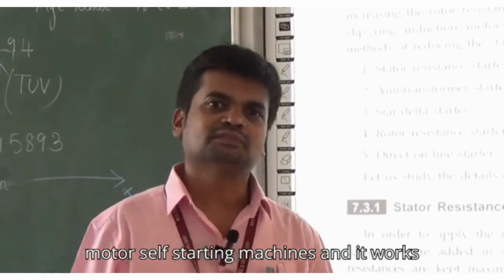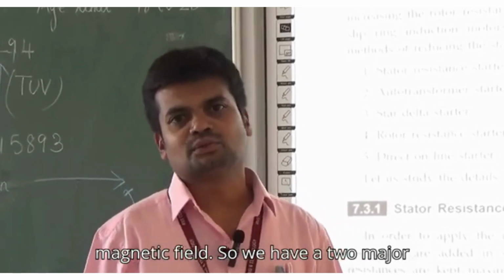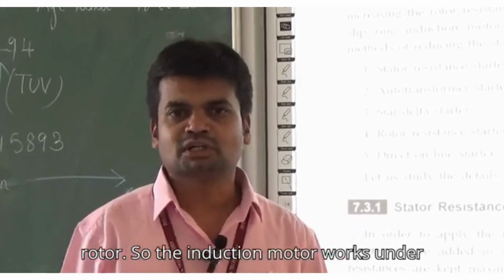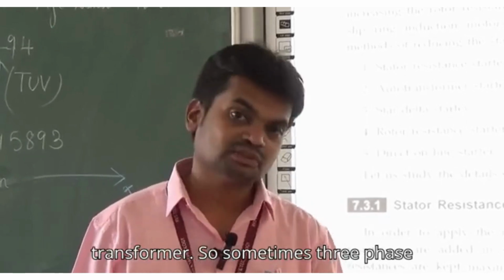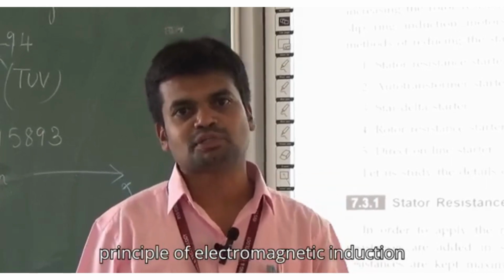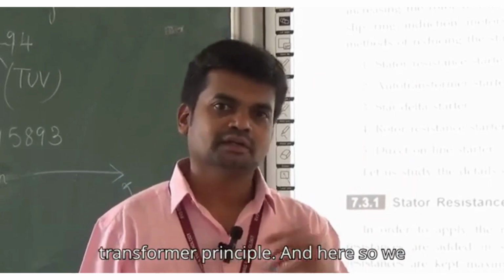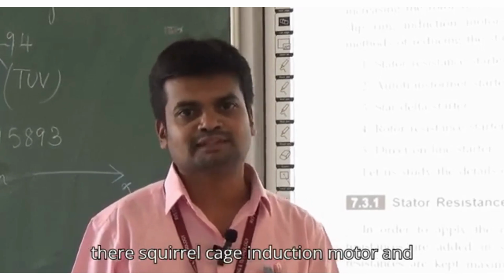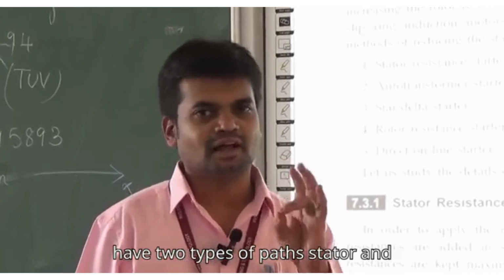the three-phase induction motor is a self-starting machine, and it works under the principle of electromagnetic induction with the RMF, rotating magnetic field. We have two major parts in the induction motor, stator and rotor. It's like a transformer, so sometimes the three-phase induction motor is also called a rotating transformer, because it works under the electromagnetic induction principle, which is the same as the transformer principle. And we have two types of rotor construction: squirrel cage induction motor and slip ring induction motor.